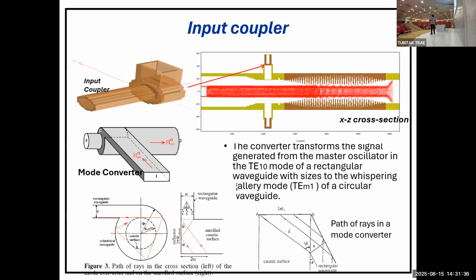So usually what we do is design and get an idea, and then we have one run that has a very fine or refined mesh, and wait for it for days maybe. It takes a very long time. Especially for PIC code, once you introduce particles, you sometimes wait for 2 weeks for your simulation to be calculated. And if you have a power outage, you start from zero. Everything is gone.